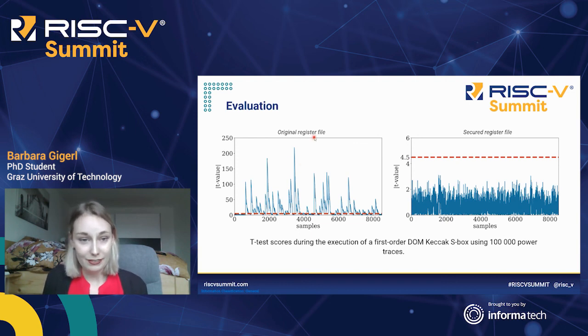And we can see that for the original register file, we see at several points significant peaks in the t-test value. However, in the secure register file, we see that there's no peak above the significance border. So we are pretty confident that our proposed fixes are really secure.